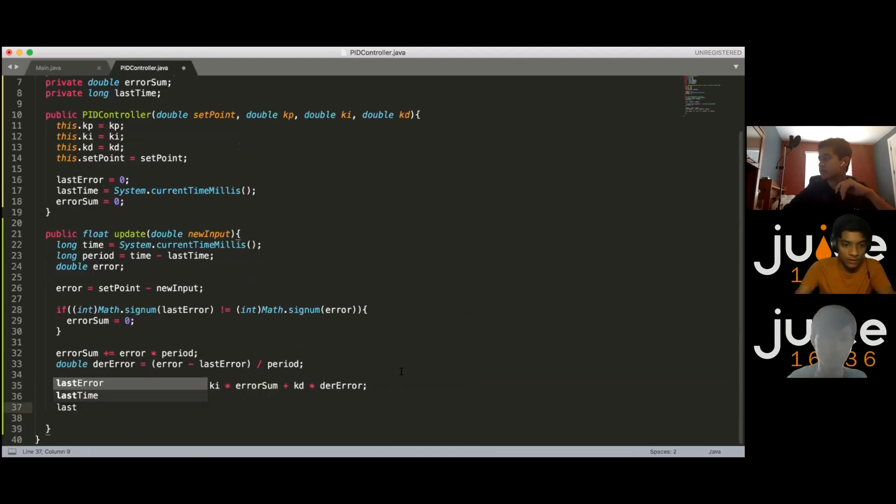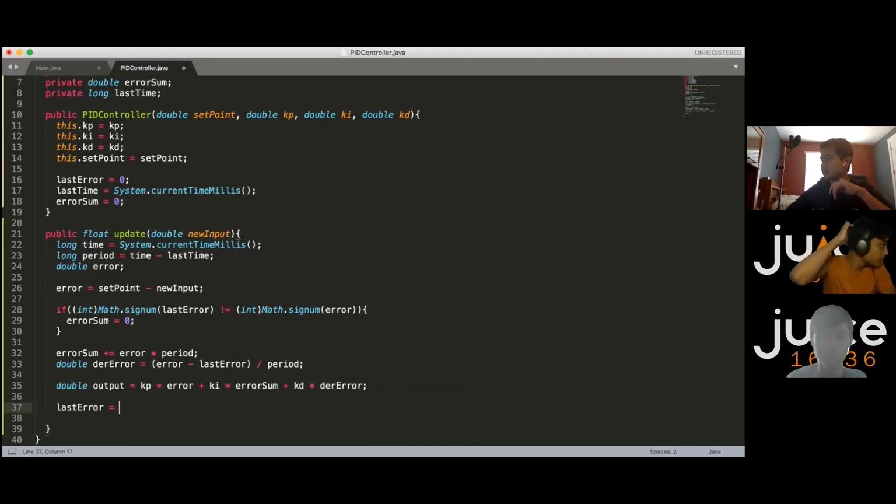And then the difference between Kp and Kd. Kp is the constant that's applied to the proportional portion. The proportional thing is just some ratio of the current error at that time. And Kd is the constant that's applied to the slope of the error versus time function. Meaning Kd should normally be negative because you should be subtracting the slope to smooth out the motion. Kp should be positive because you're trying to actually reach your target. Does that make sense? If not, then just send another question. I could try and rephrase it.